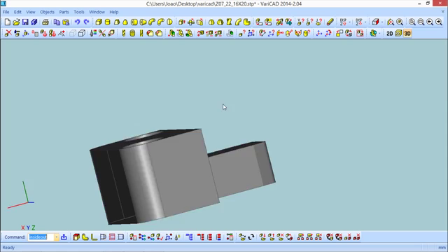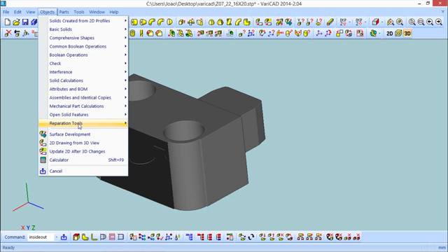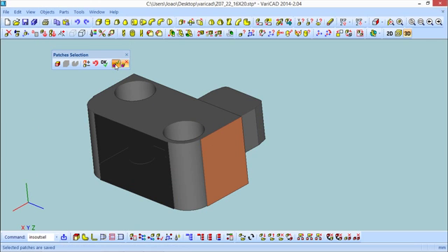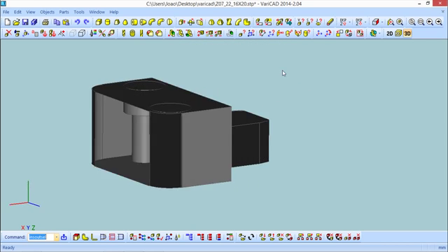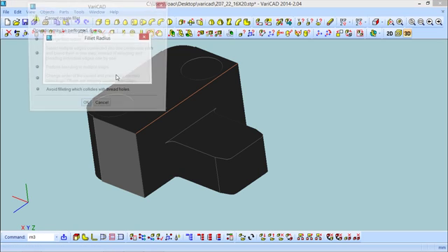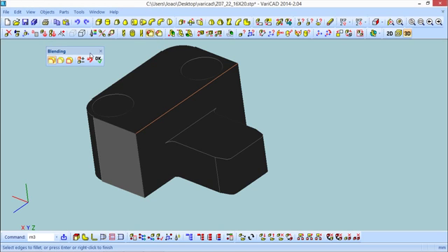In this particular case I would like to go to the last function and say, instead of reverting everything, just revert some. Okay, I'm reverting all with that exception. So let us try now, because there was a mathematical issue. Now it has problems because some normals are outside, some normals are inside, so it cannot make the calculation.